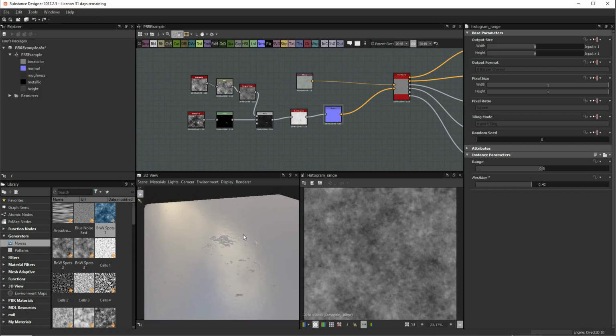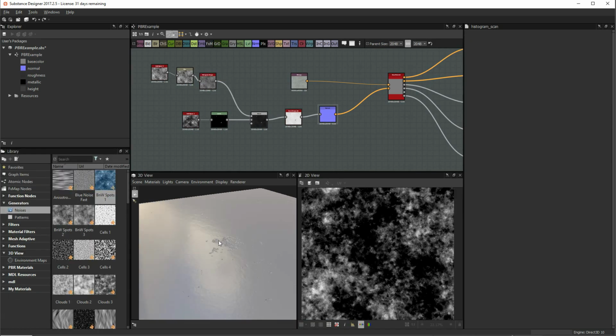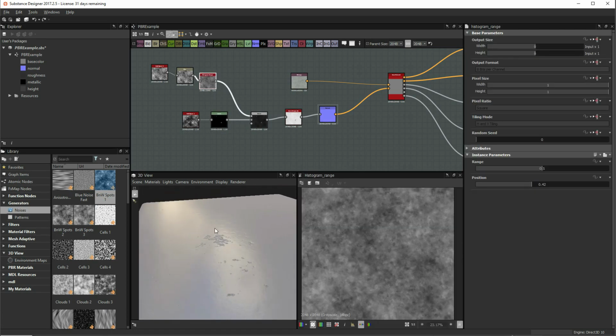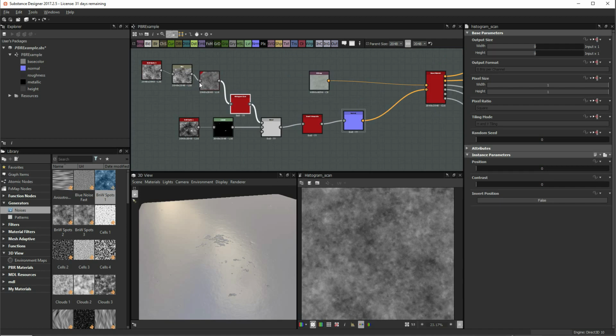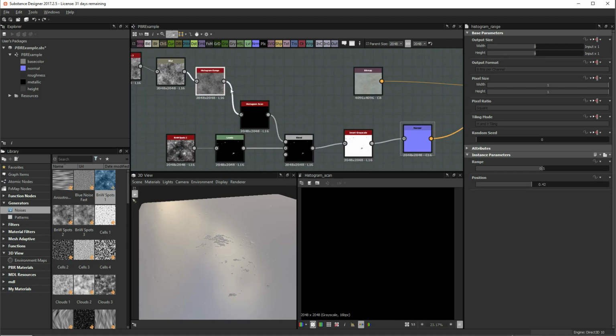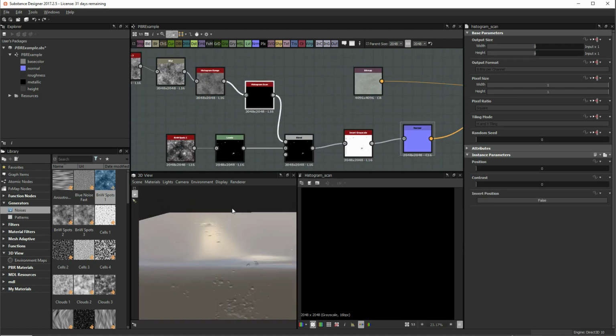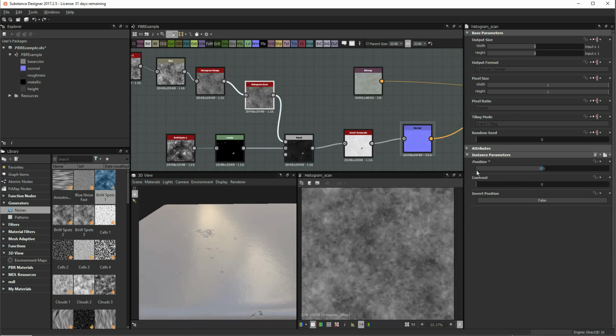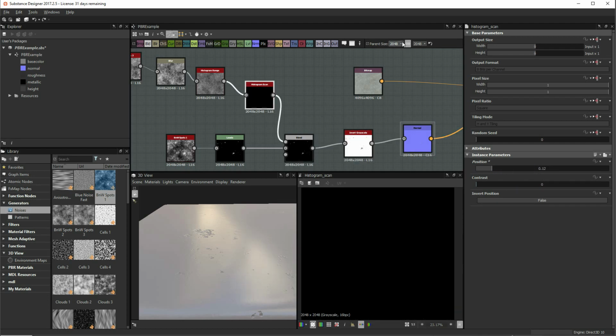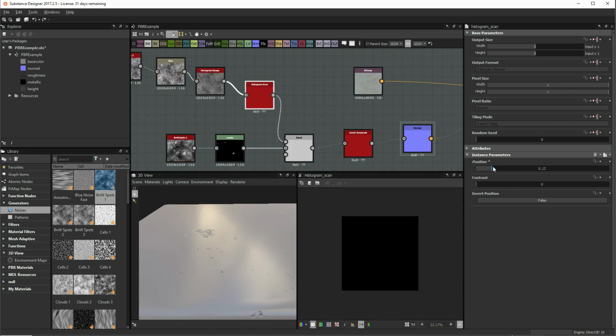we'll play a little bit with this and we'll start playing with the roughness. Actually, I'm going to take this a little bit further and get to an effect which is not quite what I was looking for here. So let's actually add a histogram scan. We've got the histogram range here already. And let's add the histogram scan, and what that enables us to do is, if we set the position to 0.5, here you'll see that, when it's at 0, it's going to be completely black. I'll reduce the resolution a bit to go a bit quicker.